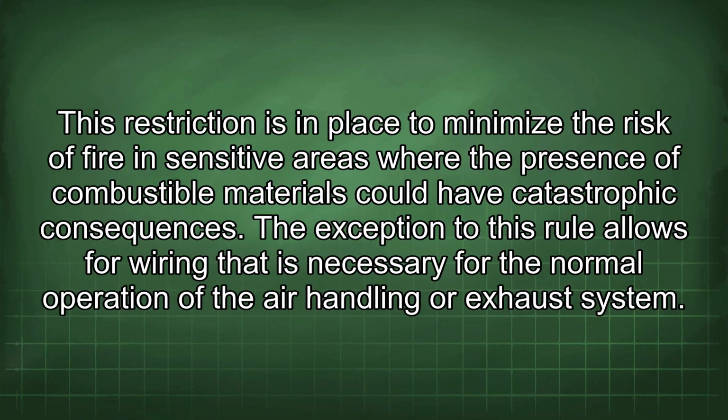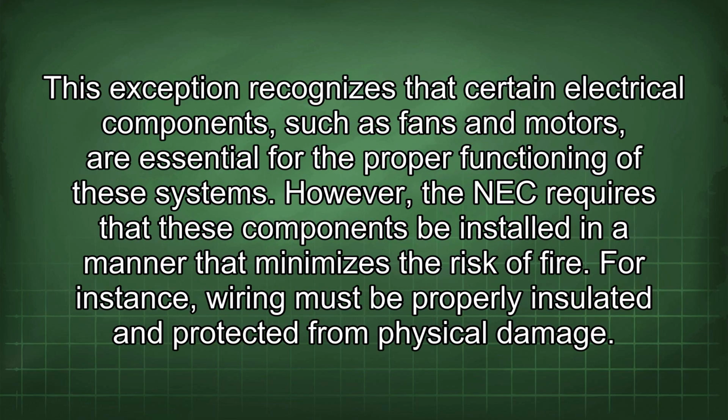This restriction is in place to minimize the risk of fire in sensitive areas where the presence of combustible materials could have catastrophic consequences. The exception to this rule allows for wiring that is necessary for the normal operation of the air handling or exhaust system. This exception recognizes that certain electrical components, such as fans and motors, are essential for the proper functioning of these systems. However, the NEC requires that these components be installed in a manner that minimizes the risk of fire.